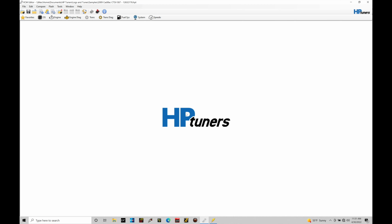Now normally when we're doing our calibrating, and I've demonstrated this in many other training modules in our Gen 4 course, we turn off that checksum for the P0068 and we raise all the table limits out of the way so we don't have to worry about it getting in our way and shutting the throttle down when we're doing our tuning process. Because at that point, as we're calibrating our airflow model and getting things sorted out, we don't know how much airflow is being ingested into our engine, so we can't populate the tables out properly. But once we've dialed things in, we want to turn back on that airflow correlation checksum so that it is going to recognize a throttle runaway situation.